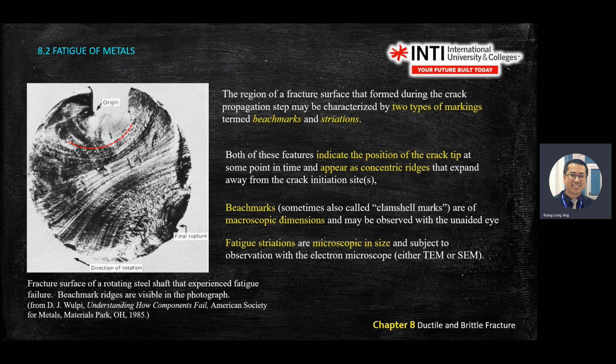They are macro. But fatigue striations are microscopic in size, subject to observation under SEM.